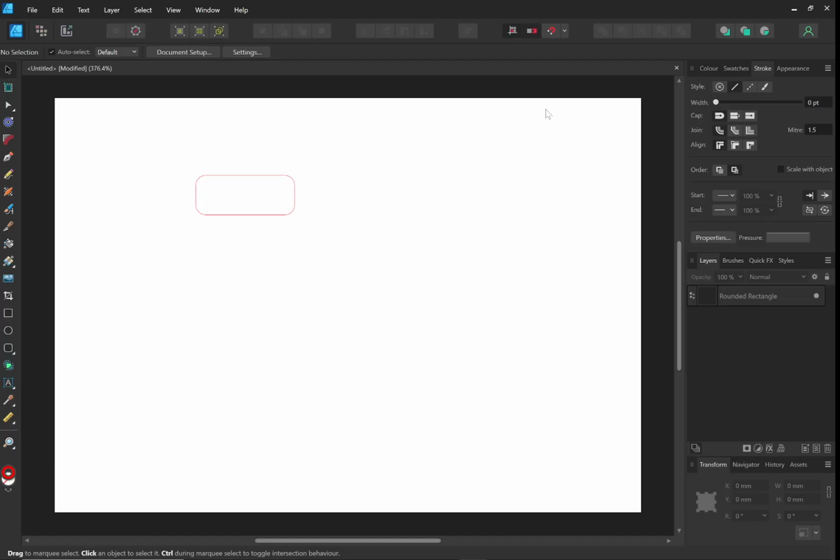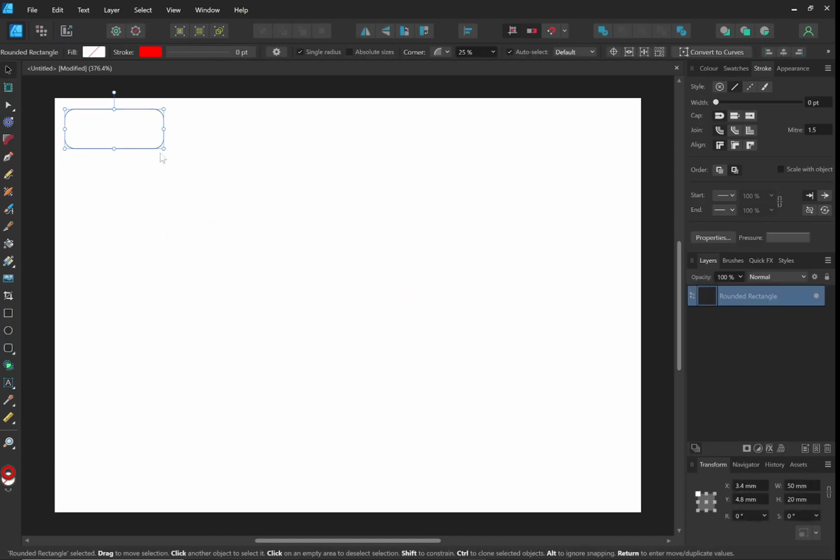This is going to cut out a little tiny rectangle. Also, I have this in a random section of the page, right? If I wanted to be very efficient, I could move this over here into the corner. But when it goes to the laser cutter, it doesn't actually matter where it is. It's just going to draw the lines, and I can move it around on the laser cutter later. So I only care about how parts are close to each other if I'm putting multiple parts together. But I'll move it in the right part of the laser cutter because I'm also going to move the piece of wood or plastic around on the laser cutter. So I need to match it to where that material is.